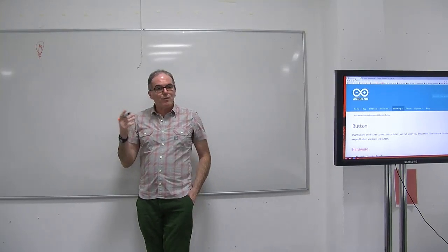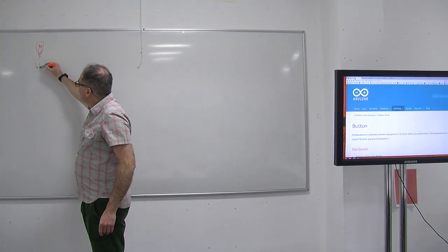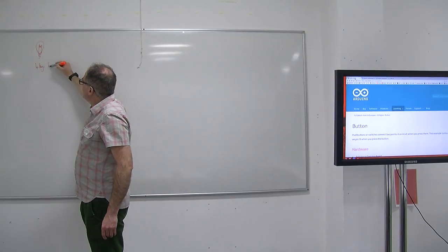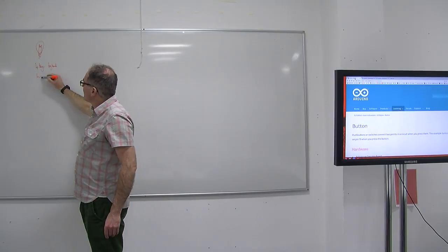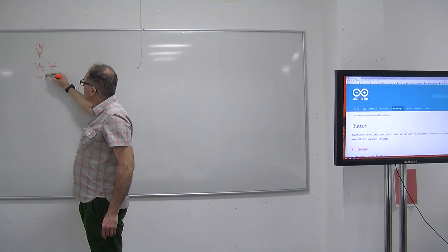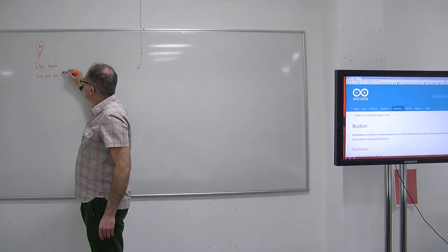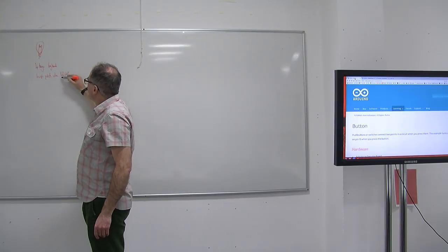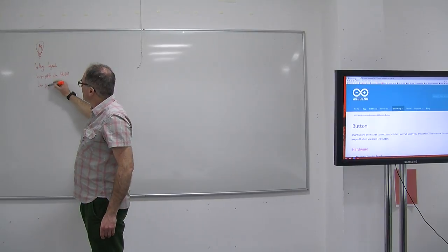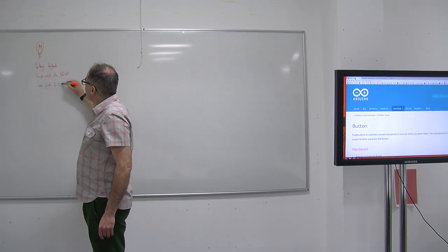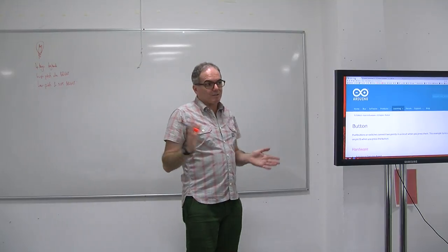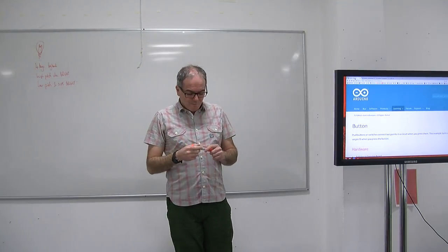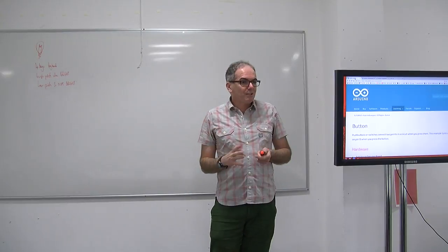And we wanted to do a 4 keys keyboard, and you wanted high pitch when bright condition and low pitch when not bright. Yeah? That's how we started. So first thing we did what I call the logic table.